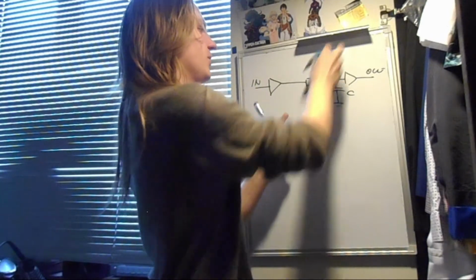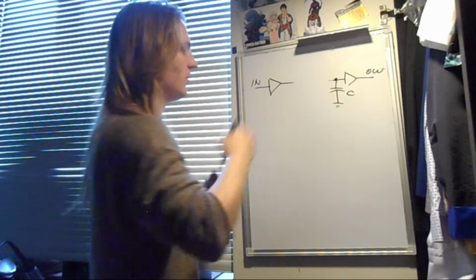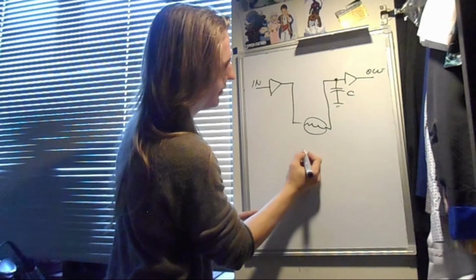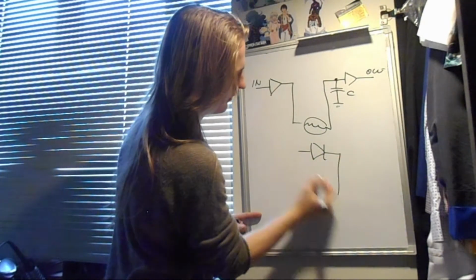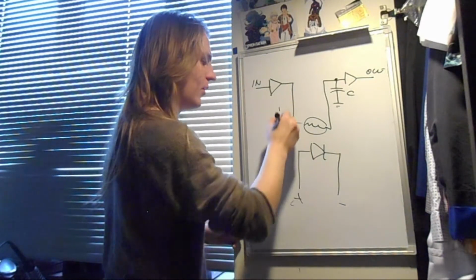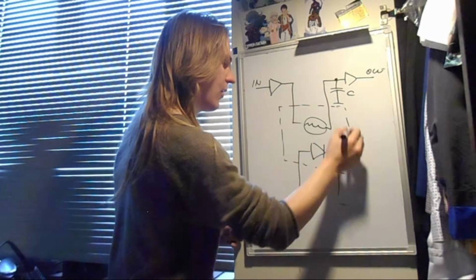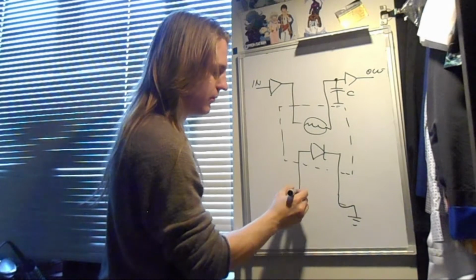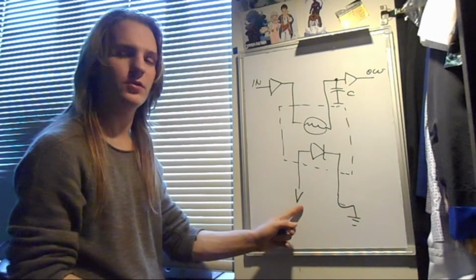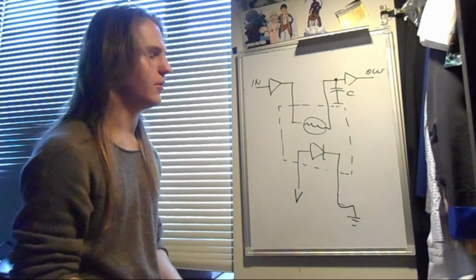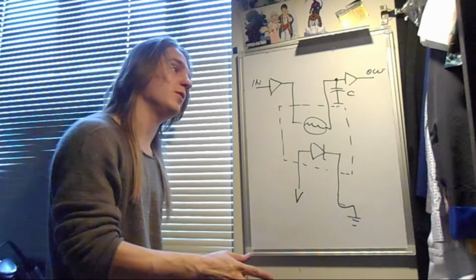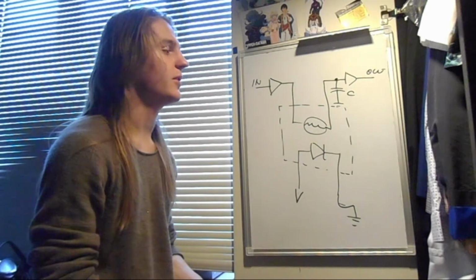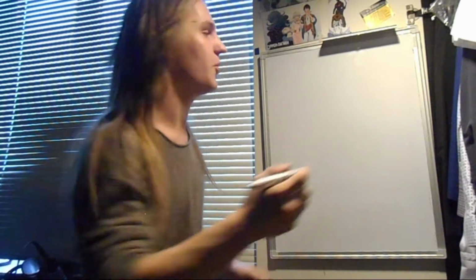What we do right there is we simply remove this resistor and replace it with our photoresistor, and here we put our LED, plus minus, put it into the light-proof enclosure, put this to ground, apply some voltage right there, and depending on this voltage, the resistance of this photoresistor will decrease or increase, hence changing the voltage charge or discharge rate of this capacitor. Magic!